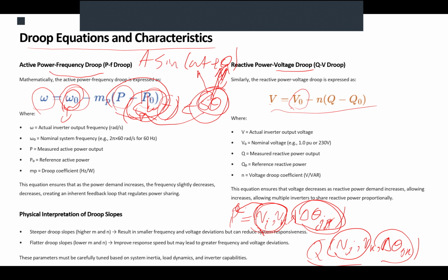So you observe the deviation in the voltage, you add Q, or decrease Q, and cancel out that deviation. So again, V equals V0. Same goes for the P. Make sense? It's like a feedback control.